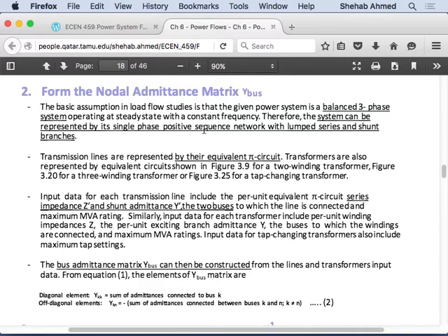We said that the transformer, let me skip this point and come back to it. So transformers will be represented using their equivalent circuits. We came up with a few equivalent circuits, either with the phase shift considered or without the phase shift considered, and basically it was a series impedance. For transformers, we had a series impedance, and if we had no phase shift, star delta, the only thing was the series impedance. If we considered the phase shift, then it was a series impedance with an ideal transformer with a certain phase shift, right? That was the model in per unit.